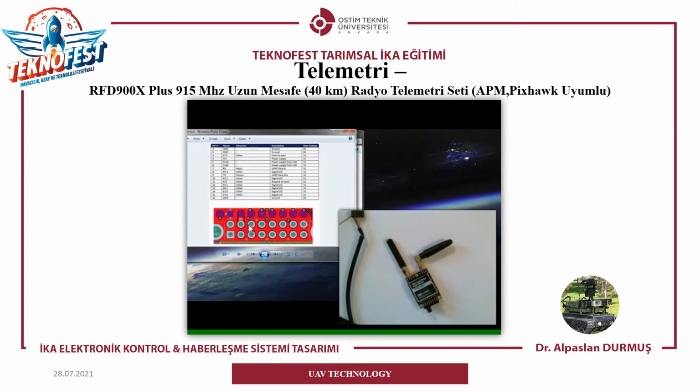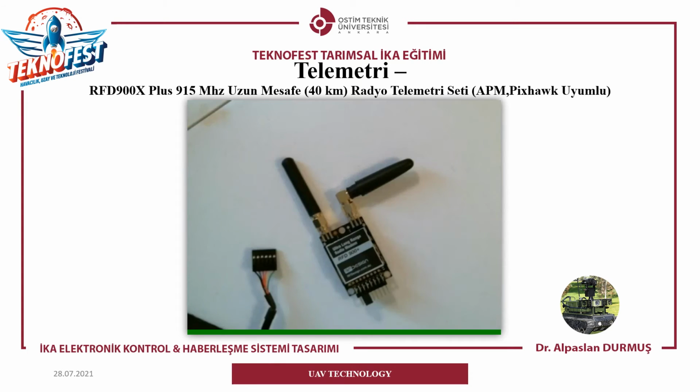Now before we connect the cable to the radio, we want to make sure we have the antennas attached. As soon as the radio powers up, it'll be trying to find other radios in the area and it will be transmitting. So whenever a radio is transmitting, it's expecting a certain amount of impedance on the output. Now per RFD's website and their data sheet, they say that 1 antenna is good enough.